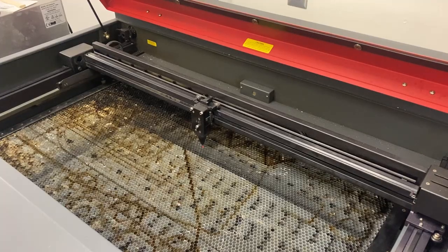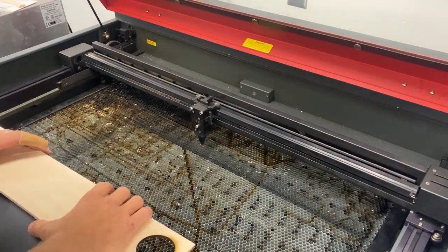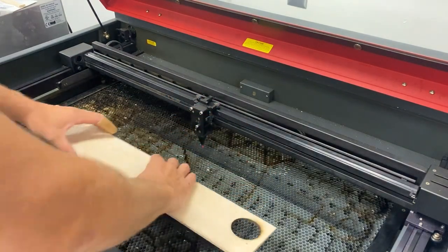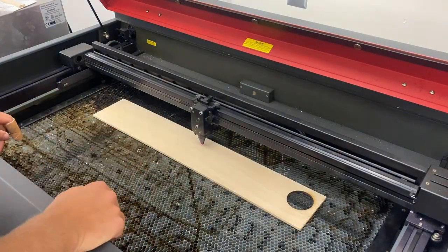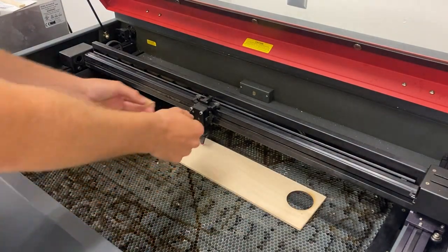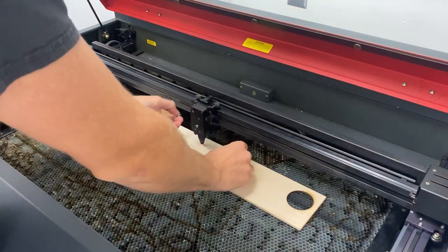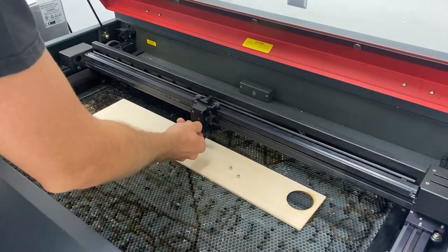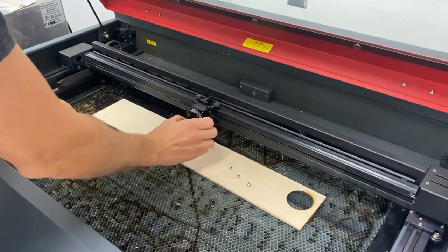All right, we have a couple things here that we're going to arrange as far as the physical settings of our cutter are concerned. What I've done is I moved the cutter somewhere in the middle of the machine, and I'm going to place our material up under it. The first thing I'm going to do is take off these 3 bolts, which will allow me to remove the lens. This is the laser lens that we're going to be using.